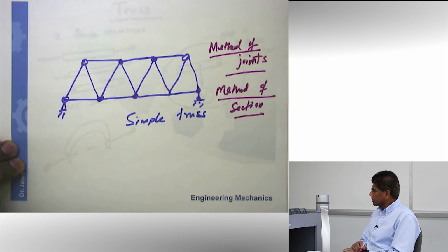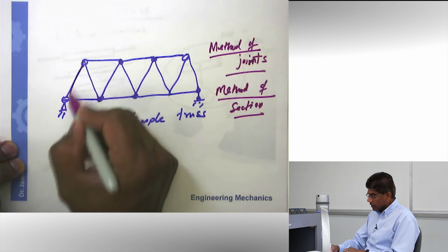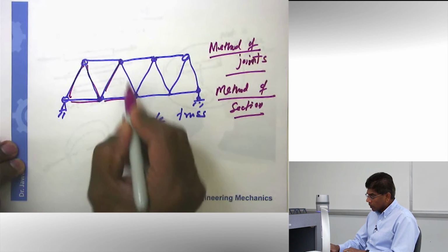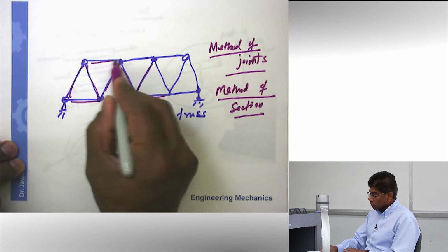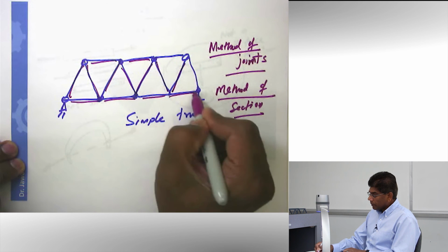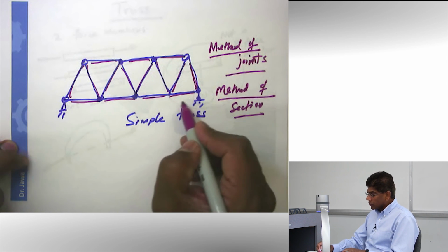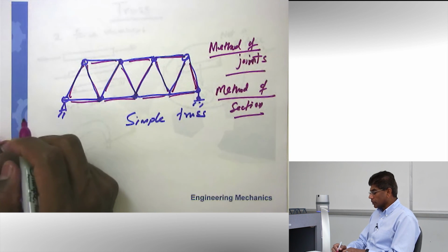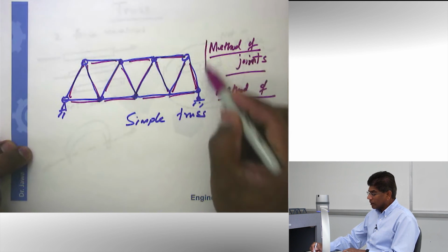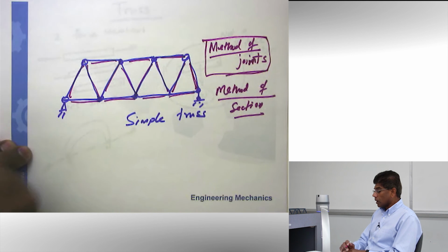And the objective of truss analysis is to find the forces in each of those members. Are they in tension or in compression? All right. So your answer should include the member forces, and in addition, you should include whether a member is in tension or compression. So let's do an example involving method of joints, and we will do this on the whiteboard.